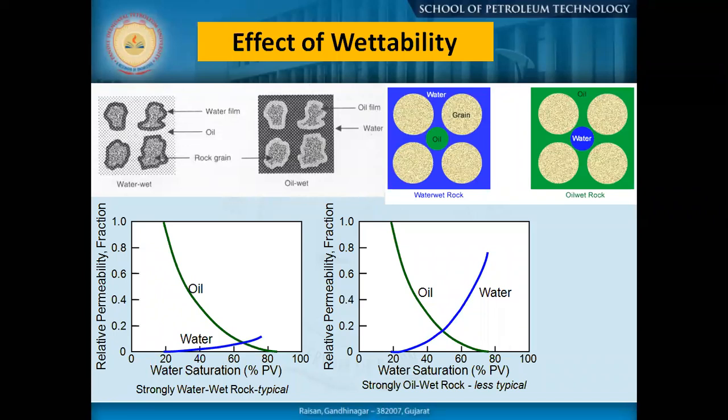So that is how understanding the distribution pattern of wettability, as well as the pore distribution and the respective relative permeability graph, matters, because what is our role as an engineer? Nobody will give you these graphs. You need to generate the graphs, or correlate your reservoir behavior with certain demonstrated graphs, and from that predict the behavior.